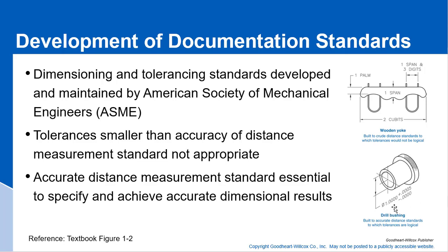So if you look at this drill bushing here, this is a 1 inch diameter with a plus 5/10 tolerance. That's 0.0005. I call that 5/10. If it was 0.005, I would call that 5/1000. But this is plus 5 minus 1. This is a very tight specification, and you would have two things. You need to be able to measure that, and you need to have these tolerances defined to a standard before you can even begin to conceive of creating a drill bushing that's dimensioned like this.